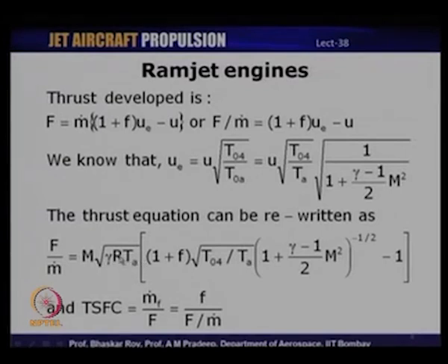Similarly, once you find the thrust, you can also find the thrust specific fuel consumption, which is the fuel to air ratio divided by the specific thrust. This gives you the TSFC, or thrust specific fuel consumption.